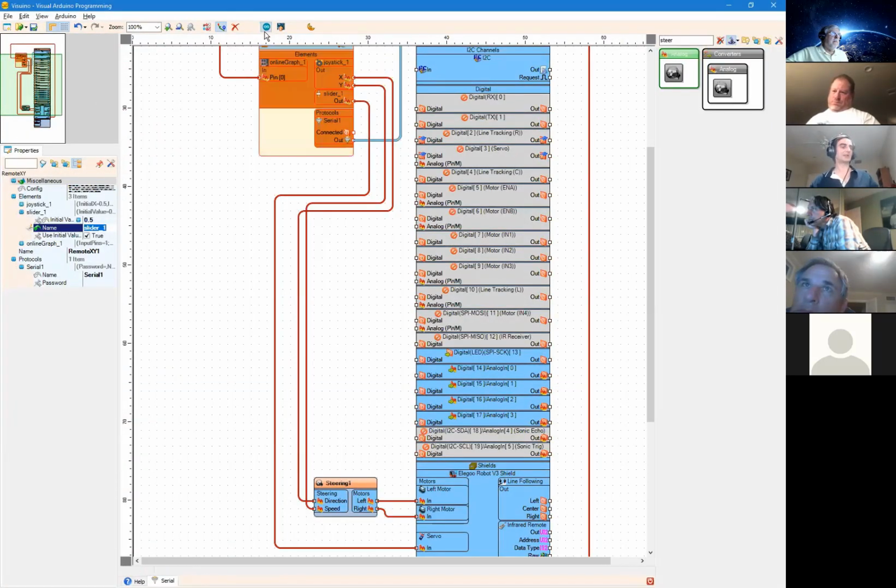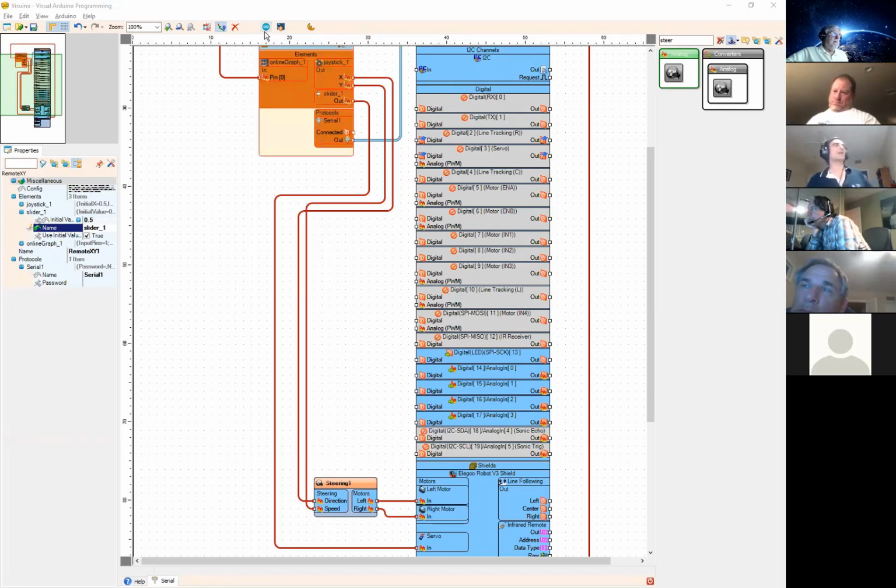So let's open it again. Otherwise the servo moves to one side and I don't like that. So I prefer the servo to be centered. Oh, you don't like driving in circles? No, it's not going to drive in circle. It simply will rotate the servo and start pushing it, and you can theoretically even burn the servo. So I just don't like that. Overloads the servo a little too much.